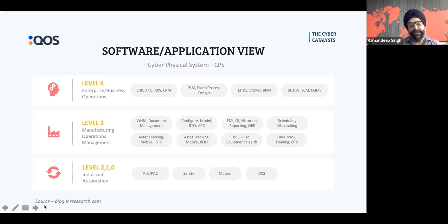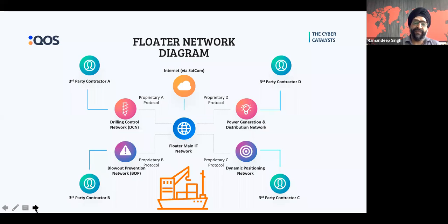Level 3.5 is typically where the IoT edge or the systems that are interacting publicly sit, but they are very much part of the plant OT or the ICS infrastructure. They are being placed in 3.5, and then 2.5 are the system firewalls, which segregate the OT layer from any kind of compute power of IT that is going to interact with that OT infrastructure. But this is more or less a generic representation by virtue of the ISA 95 architecture.